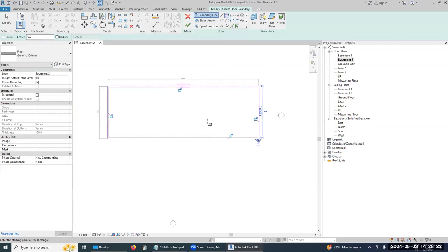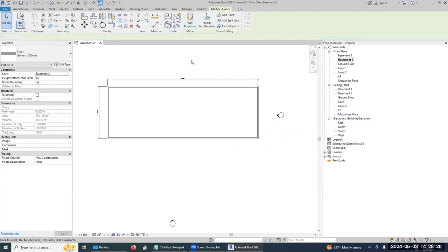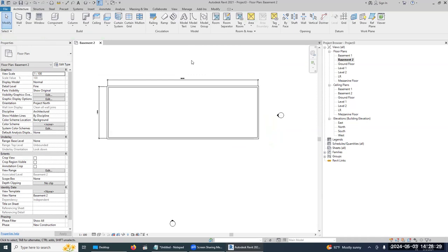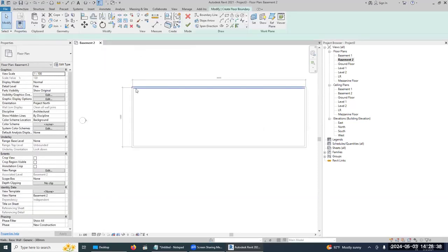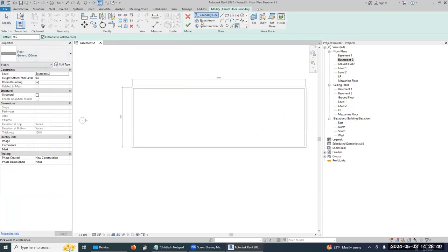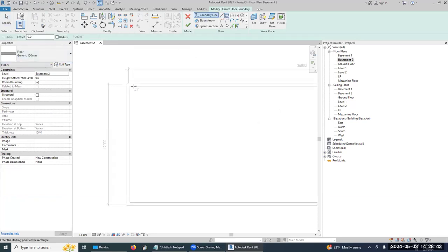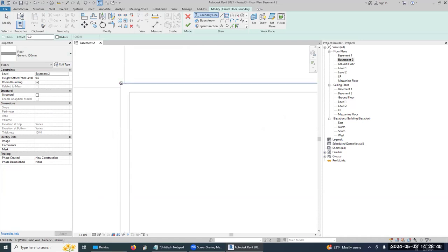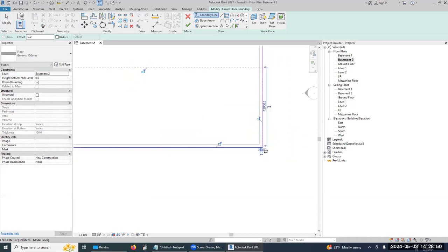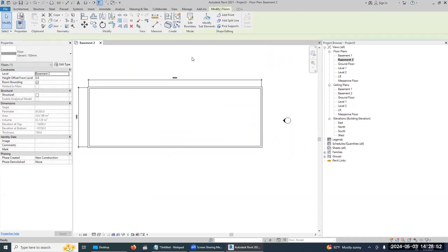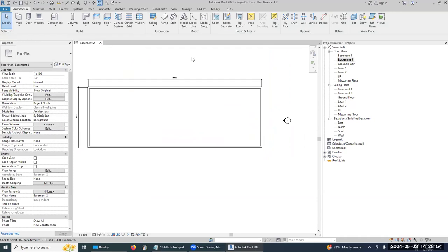This is now a floor. To connect the external points, let me show you again. Take the floor icon, 150. Using the rectangle icon, click on the external point here, and the external point here. Finally, you will say finish. There is a floor now.